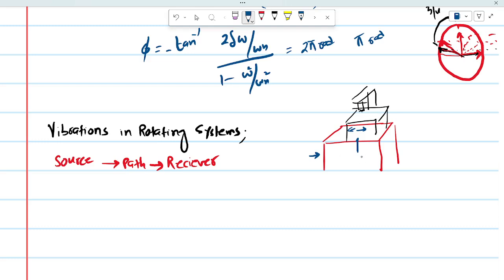So obviously you don't want the vibration or the motion to be transmitted from the table to the microscope. So you will add a vibration control mechanism between the table and the microscope, so that it will not let the motion or the force be transmitted to the microscope, so that it will not affect your reading. That's one of the examples.